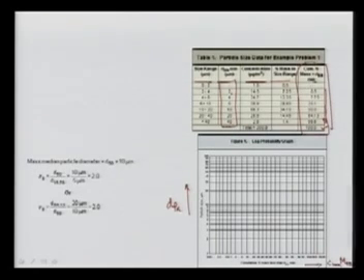Now let us plot this one. For example, see here the dPA is 2, this value is 2. So let us go to 2, and what is the cumulative mass? 0.5. So I go from 0.5 and plot this point at this dot. Let us go to the second point, 4. At 4 the cumulative mass is 7.75, so 7.75 will be somewhere here.